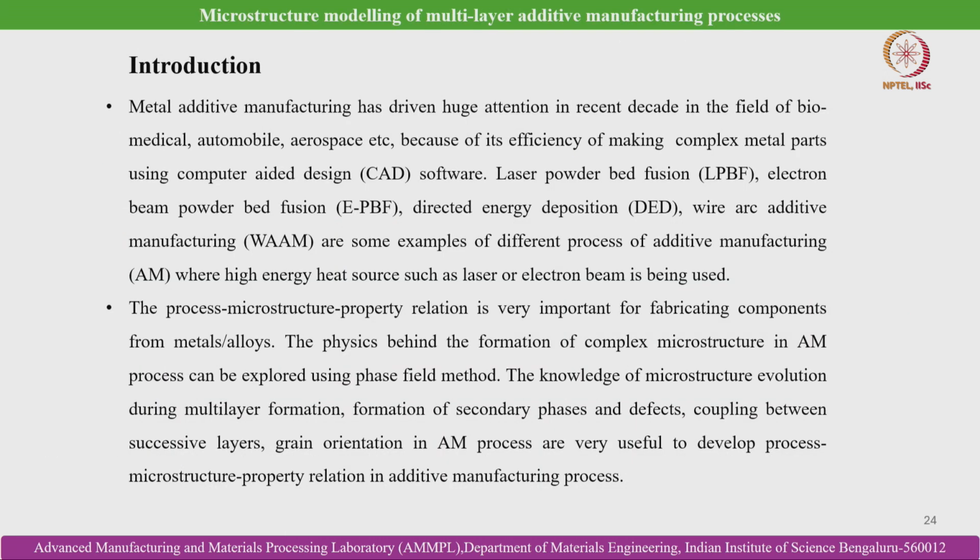So now we have already discussed the essence of the process model to understand the thermofluidic conditions, and also the solidification micromechanisms, the heat and mass transfer conditions in case of additive manufacturing. So, now we will learn how the outcome of this CFD model can be utilized as input to the mesoscopic phase field model to simulate the microstructure that evolves in case of multi-layer additive manufacturing processes.